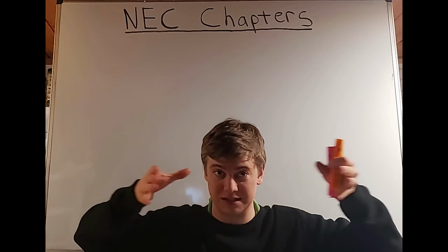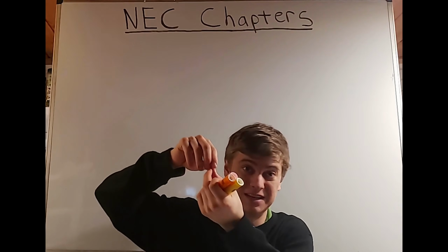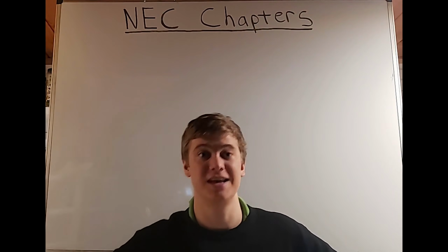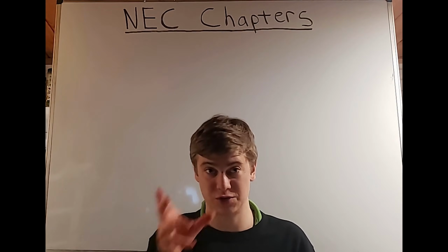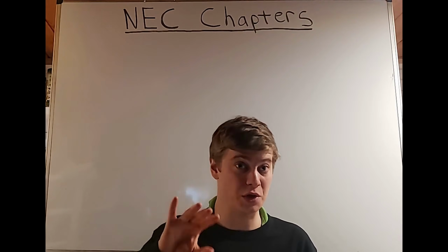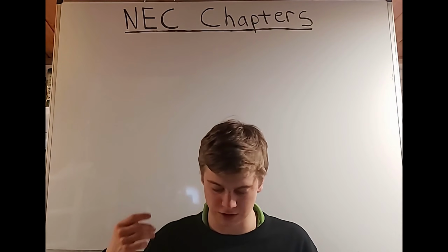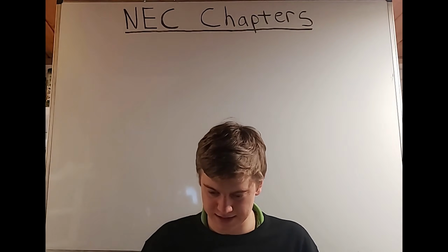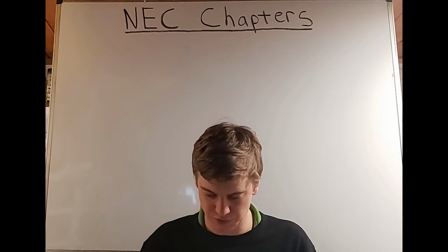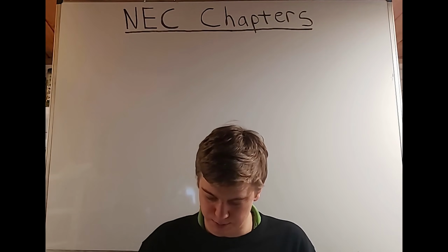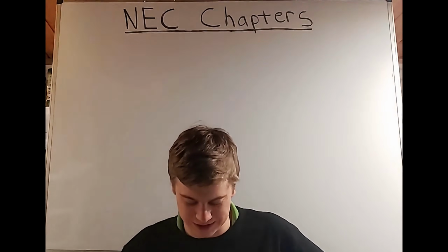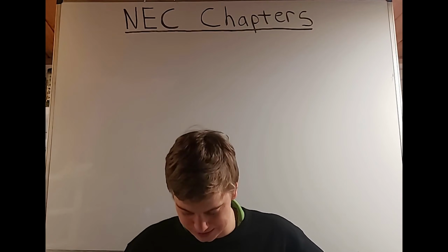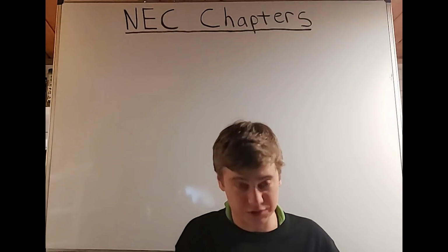So that means it could even be a 16-inch flush light, or it could be a 16-inch tall light from the ceiling down. Whatever it is, 16 inches in any direction, or 6 pounds. So make sure you highlight or, because if it's one of either of those, then you're not going to be able to support it by that screw shell. Okay, under B1, you're also going to want to read that. And then exception number 1, exception number 2, 410.36 means of support. B, suspended ceilings. Luminaires shall be securely fastened to the ceiling framing members by mechanical means such as bolts, screws, or rivets. Okay, we have article 411, low voltage lighting.